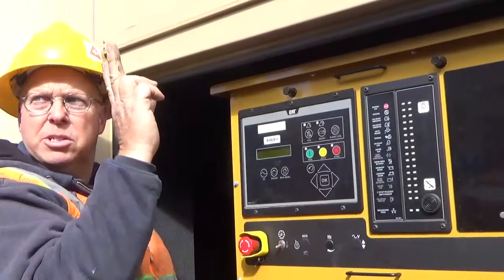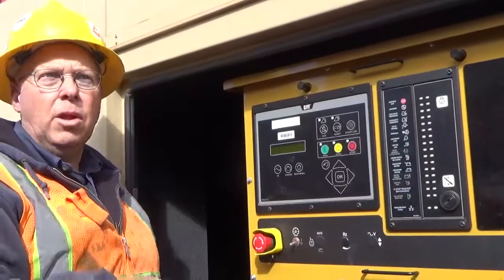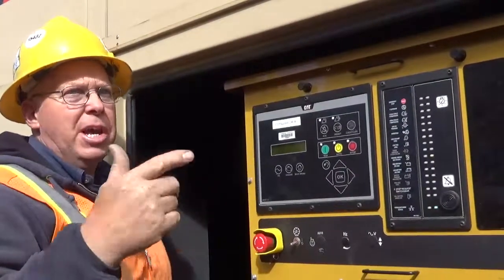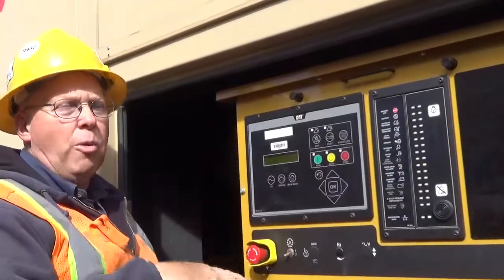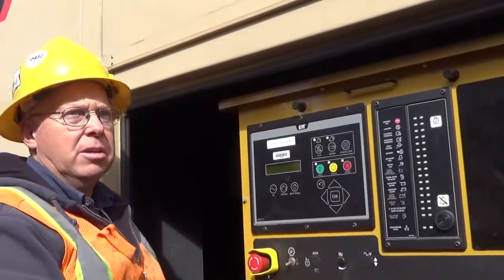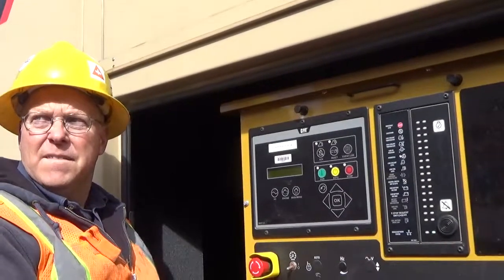So you have to basically physically go downstairs. Apparently you have those annunciators in two different places? Yeah, those are in the security and in FCC. Right. So you have to go to both of those places and acknowledge it, make it go solid. Once you make it go solid, then it'll go out on its own once you correct the condition. And that also sends a signal to the control panel that we were being trained on today as well.